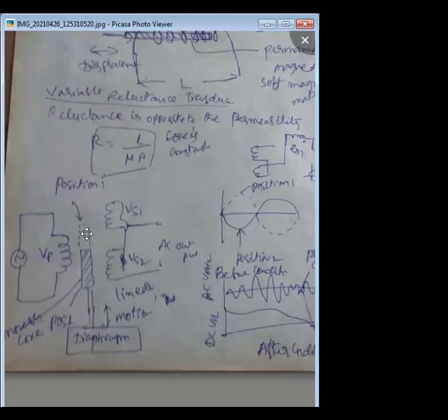Similarly, if the core is moving in the downward direction, the voltage at the secondary is decreasing. Suppose from the center position the core moves downward, then the core mostly covers secondary winding 2, and due to that most of the voltage will be produced at VS2, and the voltage at VS1 at this point is 0. Like that, depending upon the core position, the voltage will be generated.